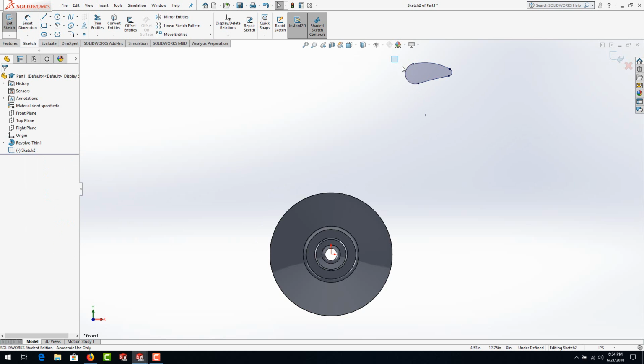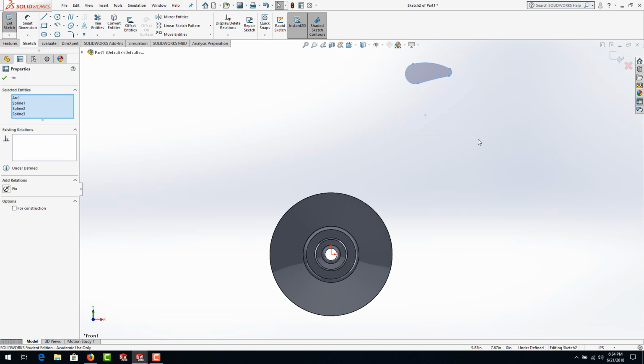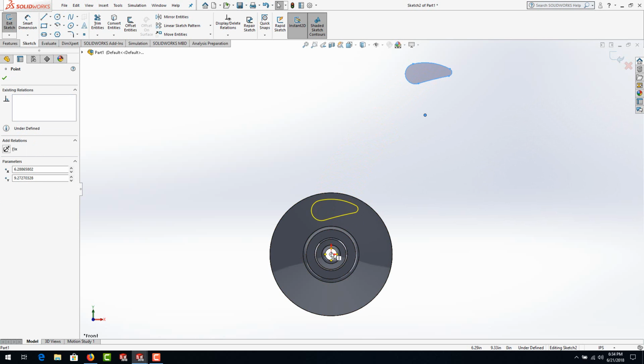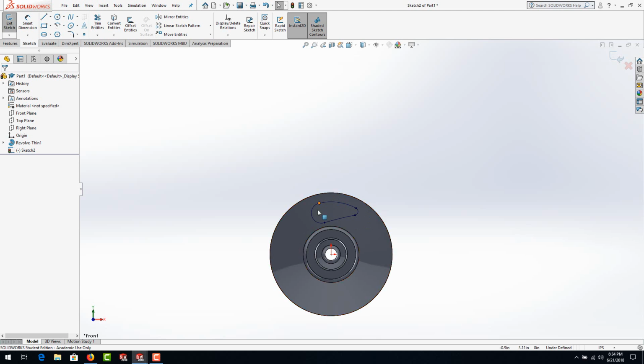Okay, now we're going to just do our little trick. We're going to drag a fence to surround this so it's in an envelope, and see that center point? That's the center point of the top arc, which just so happens to align to the center of the origin. So we could hold Control, grab this, release Control before you get there, and then once you get there on the origin, you'll see the preview and you'll get the orange dot. Release it, and now it's located.